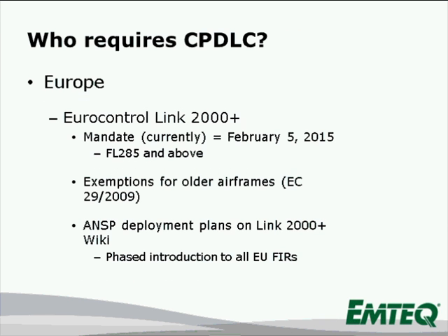As I mentioned, Europe, as many of you probably already know, there's a mandate upcoming in Europe in February 2015, which is the current date, for all aircraft flying above flight level 285. Right now, it's already been mandated for a few years for forward-fit aircraft, so any new build aircraft coming from Airbus, Boeing, or any of the other manufacturers. But this mandate applies to retrofit, so any aircraft operating within Eurocontrol airspace. And that's for equipage of CPDLC for any aircraft flying at that altitude or above.